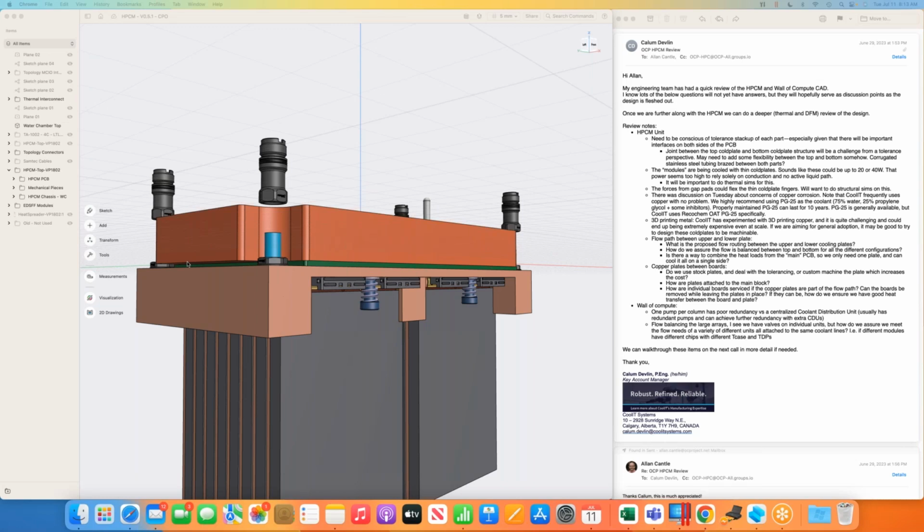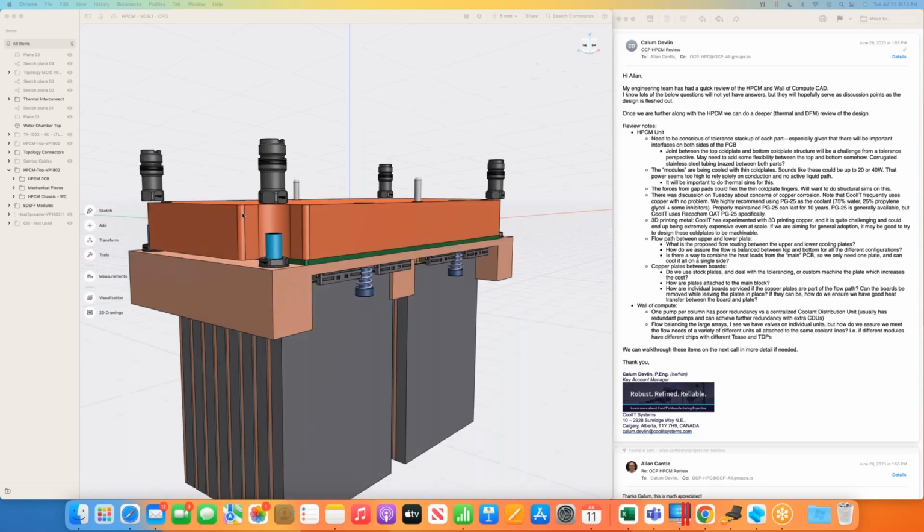The risk would be, if you have a compliant enough material, maybe you're losing a seal when you're going in a larger gap tolerance stack up. So not to say there's not material out there that exists like that, I just have not seen that in the industry. I guess just thinking out loud.